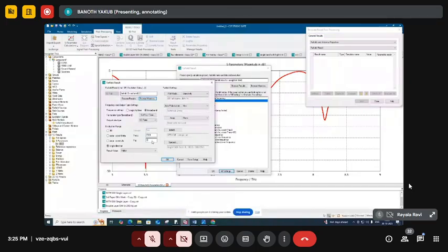For the starting stage you can give a phase angle of 10 degrees, and the plot mode you can give here as gain IEEE. For the axis polarization option, change it to ABS axial ratio theta. We are seeing the axial ratio, so select the axial ratio. Don't change anything in the other options.